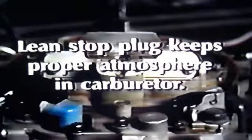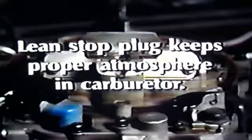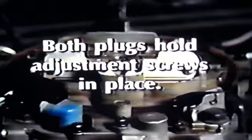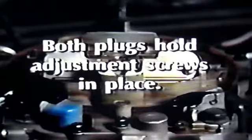At this time, we also want to be sure to replace the rich and lean stop plugs. There are two important reasons for this. First, because the lean stop hole is outside the air cleaner, it must be plugged to keep the proper atmosphere in the carb. Secondly, these plugs actually hold the adjustment screws in place so that they can't change position after we've set them.